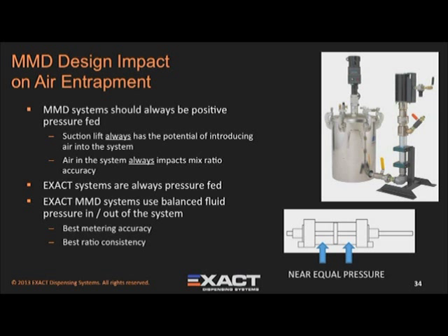The design of the meter mix dispense equipment you specify has a big impact on the likelihood that air entrapment will become a production issue. We are absolutely convinced that you should always use pressure feed to supply your meter mix system. When you pressure feed an MMD or a meter mix dispense system from Exact, we guarantee we will never put air into your material. We also have a nearly equal pressure design in our double acting systems that makes air entrapment virtually impossible.